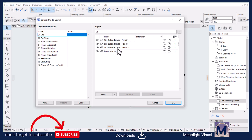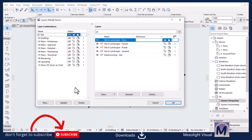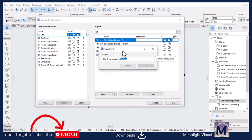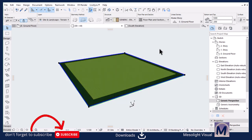I think we need a couple of layers here. We would need a layer for trees. Hit OK. Make sure it's active and then update. Another layer for site objects like human figures, just like that. Then also make it available for the site layer combination, and then hit OK.